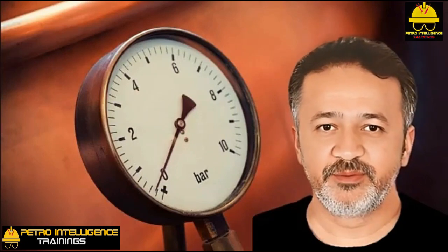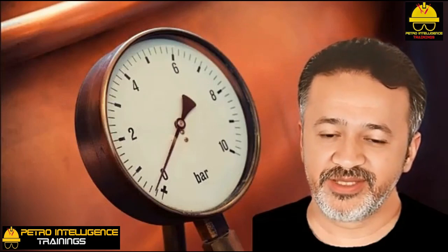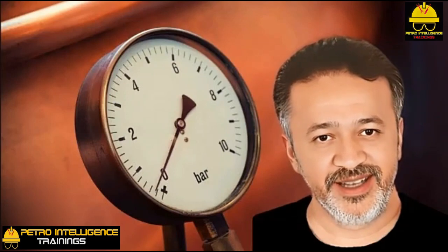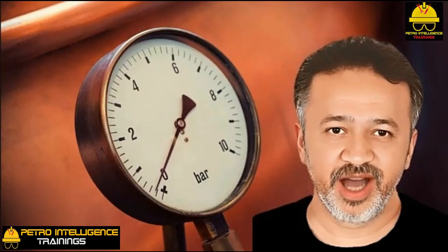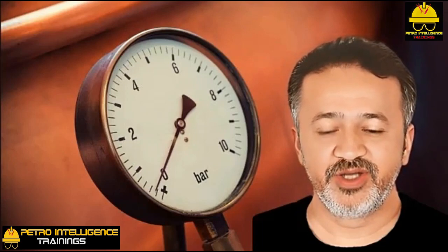For example, suppose the height of hydrocarbon liquid in a gauge glass is 4 feet between the level taps. The glass temperature is 60 degrees Fahrenheit, the tower temperature is 560 degrees Fahrenheit. How much higher is the height of liquid in the tower than in the glass? Answer is 1 foot.